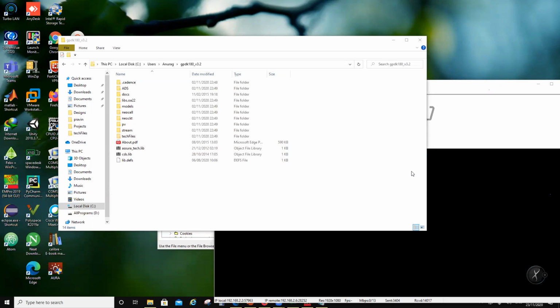When the problem space is small, for example a package design, you should use FEM. Method of moments is good for planar circuits. As soon as you add 3D to it, method of moments is not good. For example, a via, which is basically conical, you cannot use method of moments. It will be an approximation, right?